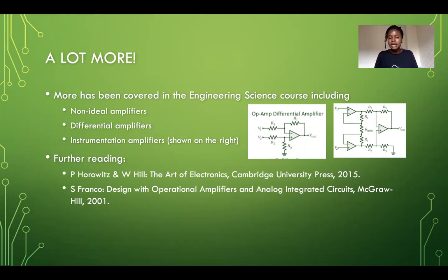It's basically the same step. You follow the voltage around. Sometimes you look at the current nodes, and then you use I minus equals I plus, and then V minus equals V plus expressions. And you should be able to rearrange. You can either rearrange step by step, or you can solve simultaneously if you want to.